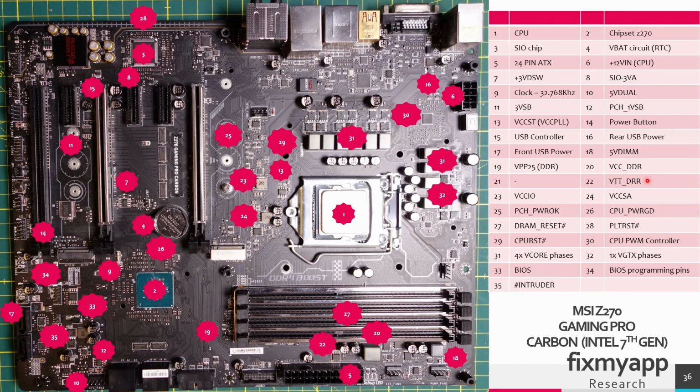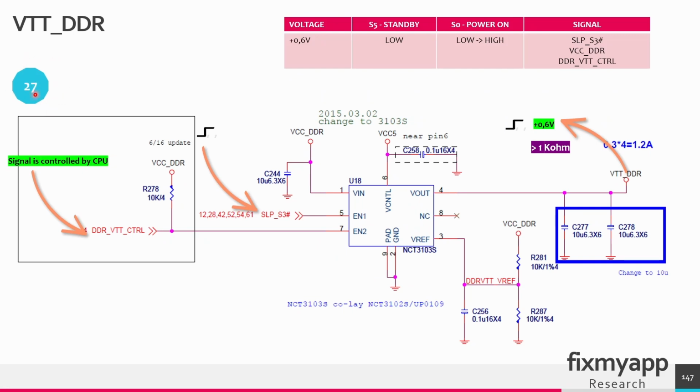This voltage is the VCC DDR power supply, so that is 1.2 volt divided by 2. So the VTT voltage that will go to the RAM modules is 0.6 volt. In region 27, we have to create the VTT DDR voltage rail, that is 0.6 volt. VTT DDR stands for termination voltage, and this voltage is used for terminating the data lines DQ for DDR memory. This voltage helps to prevent signal reflections, especially at high frequencies. Signal reflections can cause data errors, so a proper termination voltage is crucial. The termination voltage of 0.6 volt will go to the RAM modules.